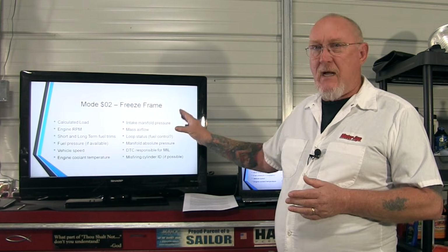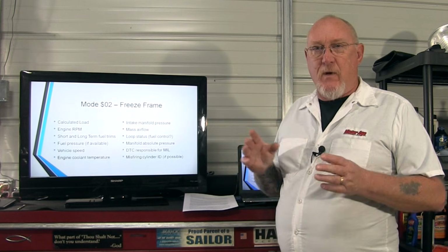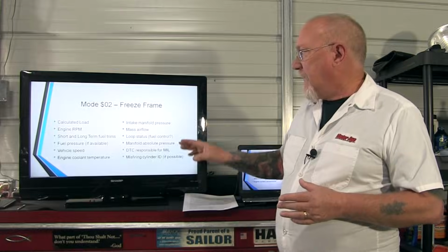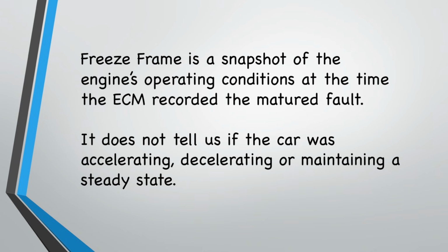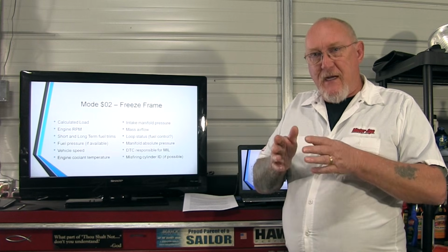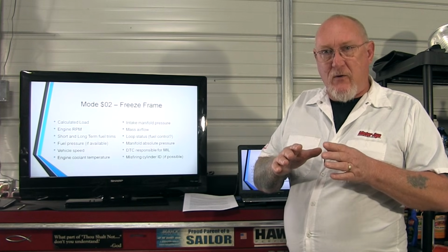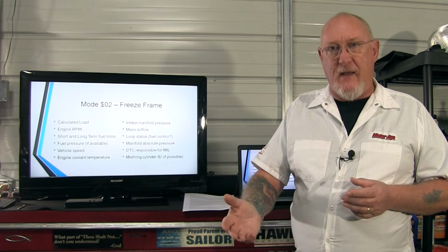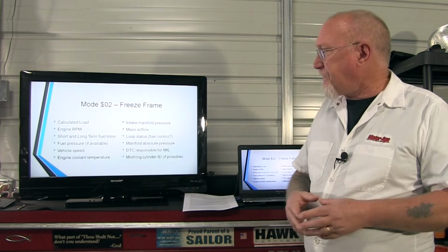And one thing we can't tell from freeze frame data is what conditions the vehicle was operating at the time. I don't know, for example, if this vehicle was accelerating or decelerating or maintaining a steady speed. So when I'm using this data to help me diagnose a problem, it's a point in time, but I need to factor in conditions that may be occurring before or after that point in time to help mimic or recreate that problem, okay?